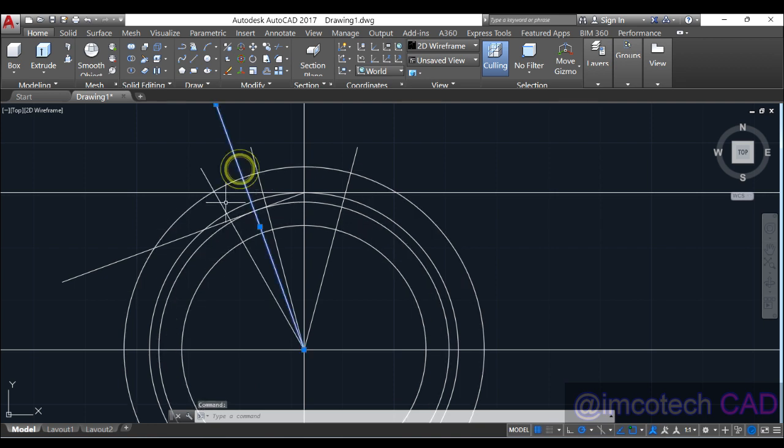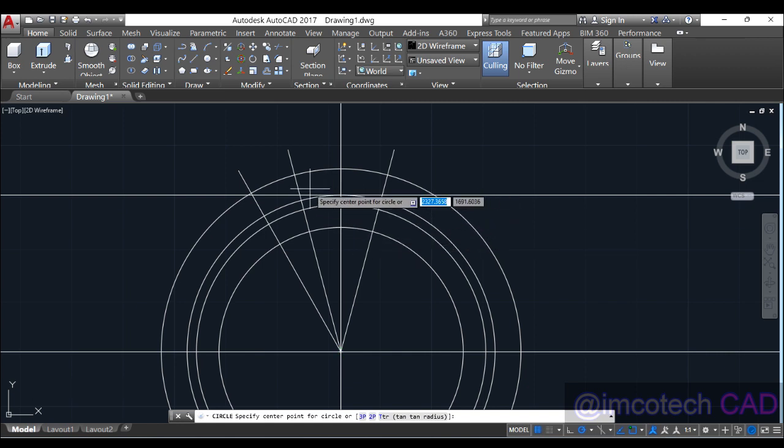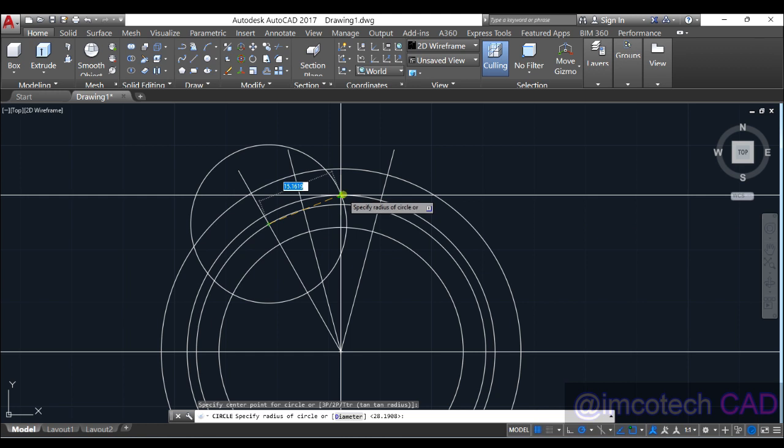Now that I'm done, I will delete the pressure angle lines. Now I have my base circle, right? And the center of the teeth will be around here. So for us to have the first center, we will take a circle and draw from this place, because we already have the location. We know that one tooth will be on this side, but the center will be here and to this point. Now we have one of the profiles. Look, from this place like this is one of the two profiles.